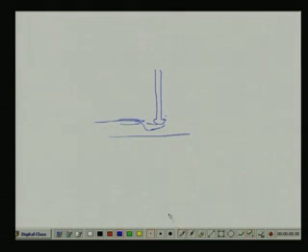Okay. Now, what will happen is that when the liquid is flowing through this one, it will flow in these directions. If the valve moves upward, there is a restriction here, so the flow will go like this, and it will flow through this one.